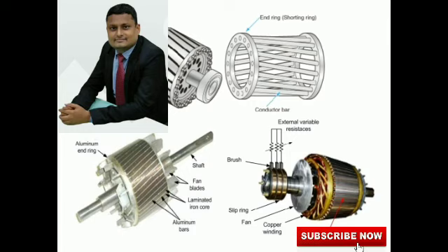Now number of rotor slots: let us take 20% more rotor slots than the stator. So SR minus SS equals 0.2 into SS. SR minus 54 equals 0.2 into 54, so SR will be approximately 54 plus 11, that equals 65. Check for the consistency.